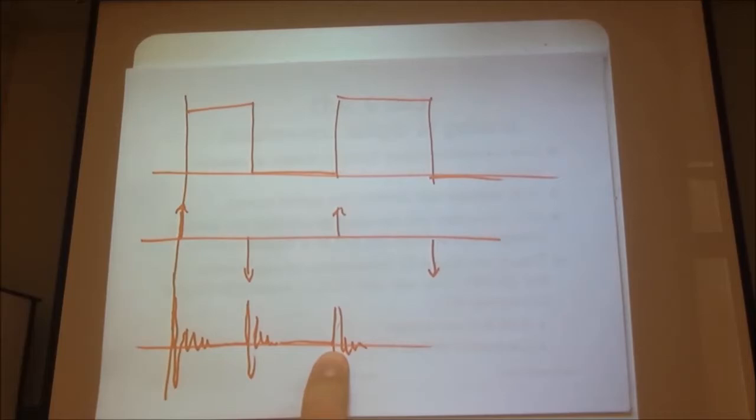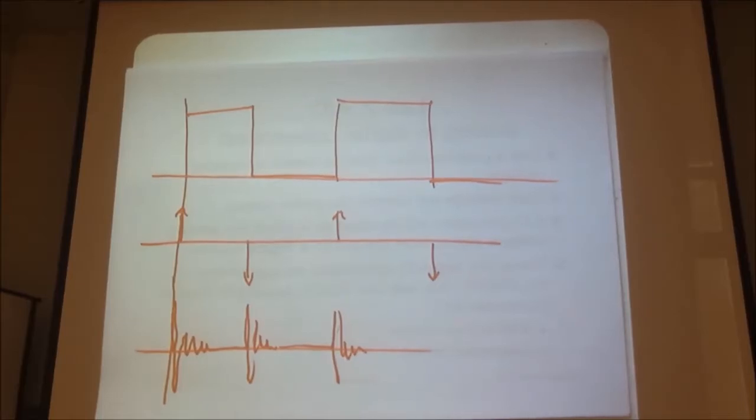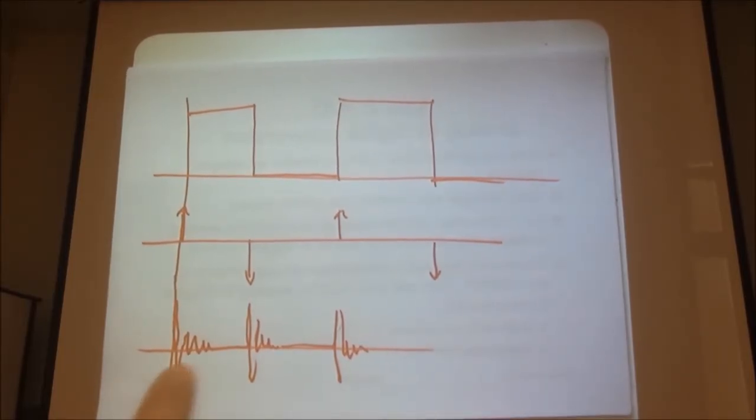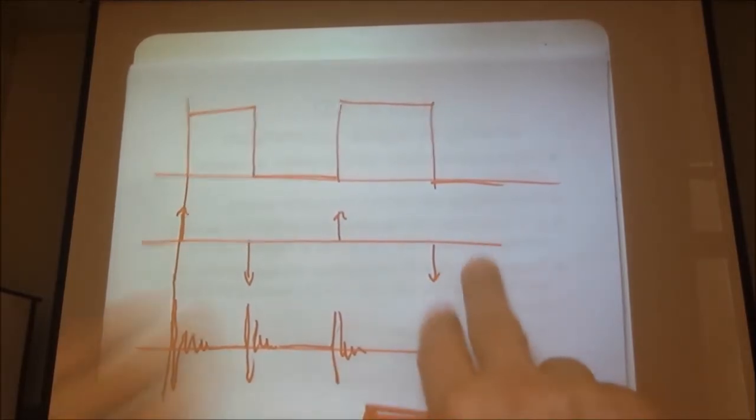Every circuit you have always has some capacitance and some inductance. Typically capacitance dominates. Those things get smaller and smaller. Inductance is becoming a bigger factor as well. Historically it was ignored, but that's no longer true. And so in a lot of second order responses, ringing exists. And the same thing with the overdamped case.